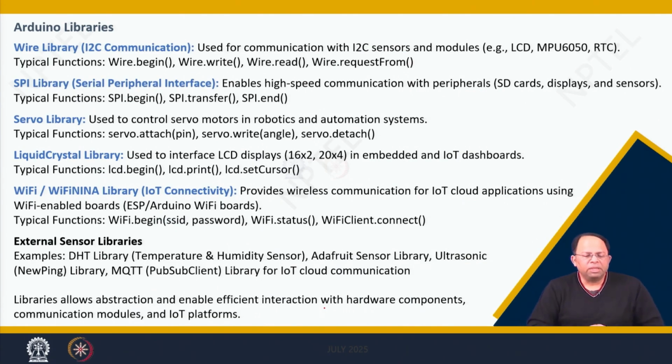Then more common functions that you will likely be adding are I2C communication, the wire library functions. This is used for communicating with I2C sensors and modules such as LCDs, MPU 6050, RTCs, and so on. We use wire.begin, wire.write, wire.read, and so on.